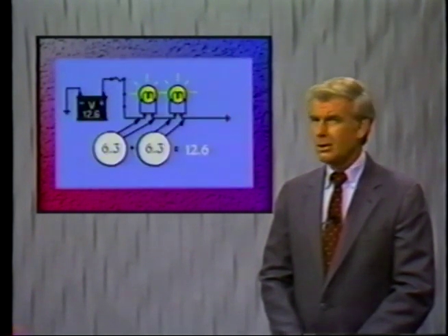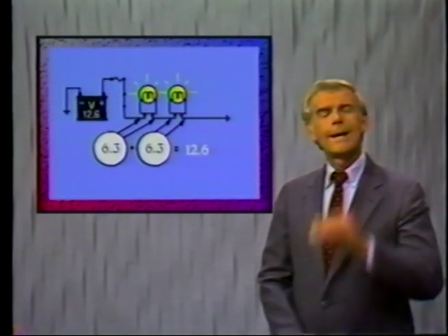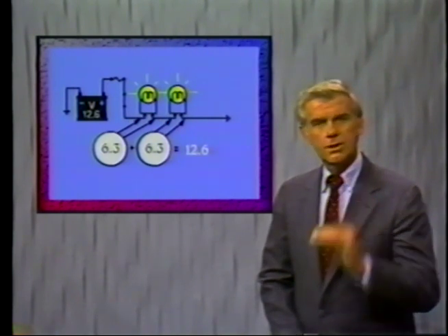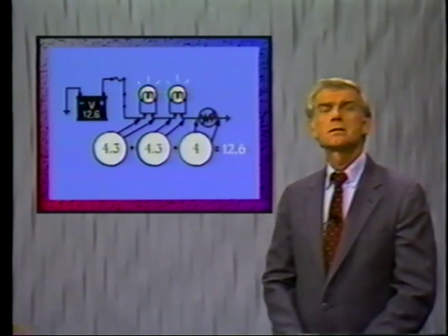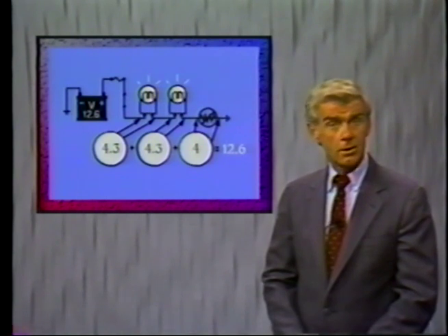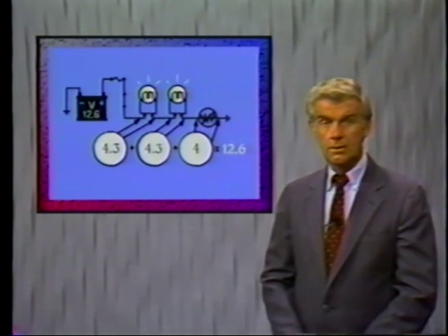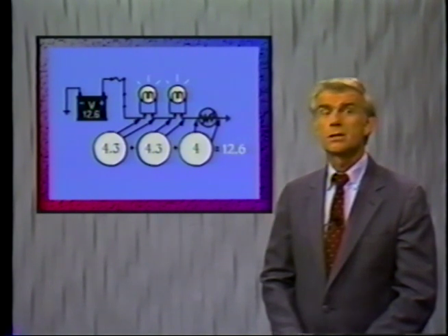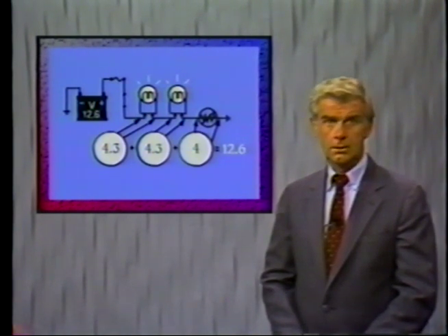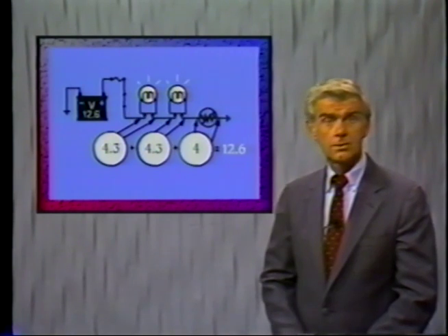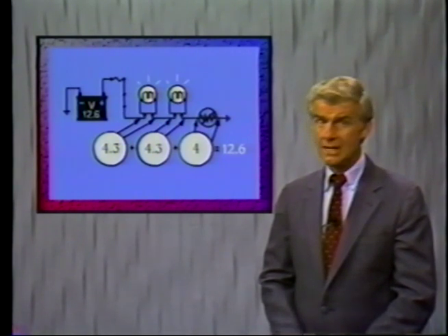As mentioned earlier, loads in a circuit are designed to operate at a given level of voltage and current. Extra resistance in the circuit acts as if there were another load device put into the circuit. As we saw with the simple circuit, the extra load shares the voltage and current available in the circuit, thus robbing the intended loads of their designed current and voltage levels.